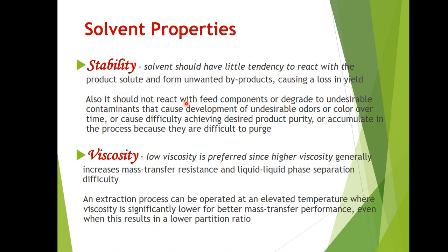Also, it should not react with feed components or degrade into undesirable contaminants that may cause development of undesirable colors or odor over time, cause difficulty achieving desired product purity, or even accumulate in the process because they are difficult to purge. That has to do with your solvent stability. It should be stable, it should not react, it should not degrade, and it should not form undesirable contaminants inside your equipment.